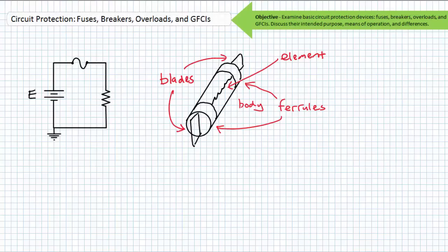When the fuse is intact, the path between its two terminals is a closed 0 ohm path, and the circuit operates as intended. When opposition decreases and current reaches or exceeds a certain predetermined value for a certain amount of time, the fuse melts, and the path between its two terminals opens and stops current flow by becoming an infinite resistance. The fuse is essentially acting just like a switch in series with the electrical device it is intended to protect. If the switch is closed, current will flow. If the switch is open, current will not flow.